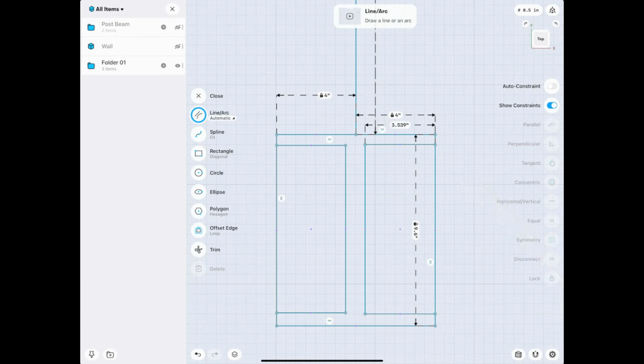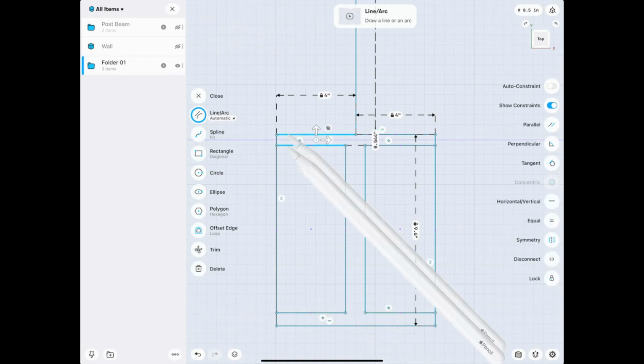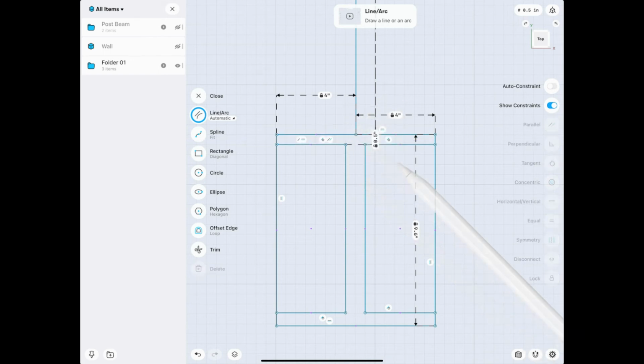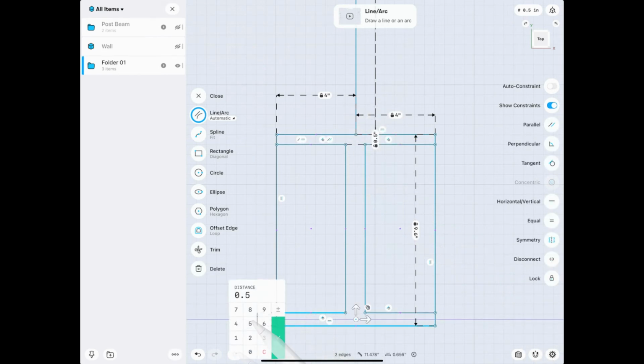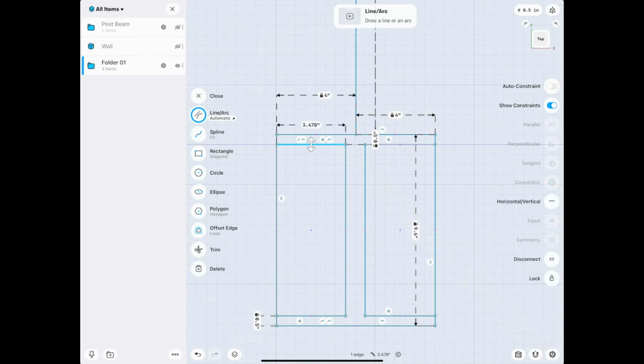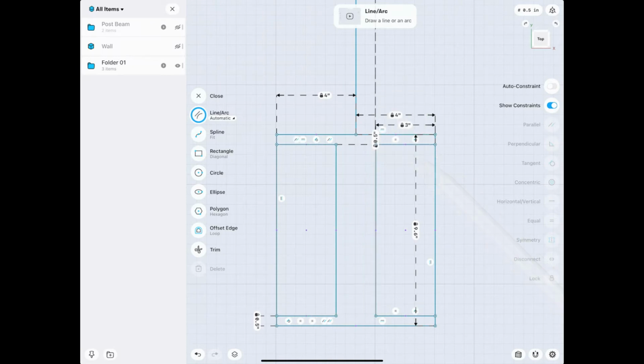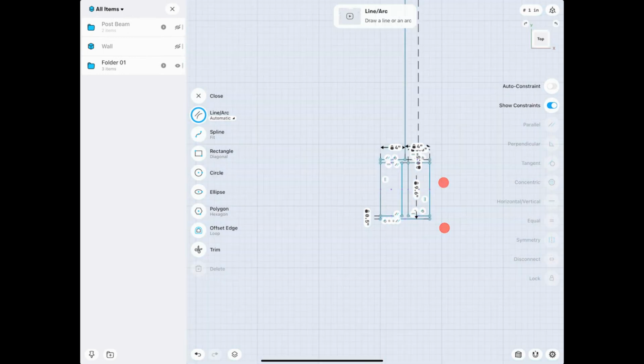Since, again, we make a concept model, all the stuff is standardized, now the thickness here. And since you're learning this process, we will simplify dimensions, etc. So here we say 1/2 inch. Here we say 1/2 inch. And what do we have there? 3.4. This should be 3.5. Very good. And then all these lines, we make all equal. So when this I make 3, you see how everything is updated perfectly. Pretty nice. Cool, no? Okay.